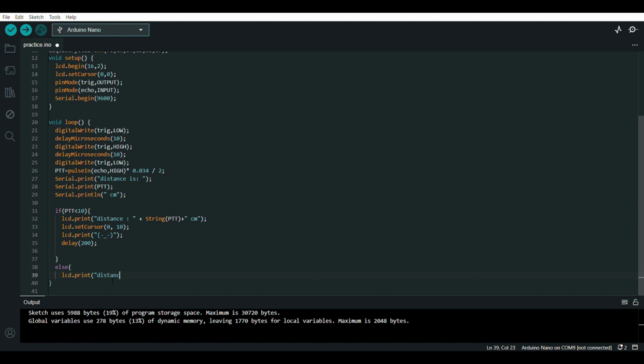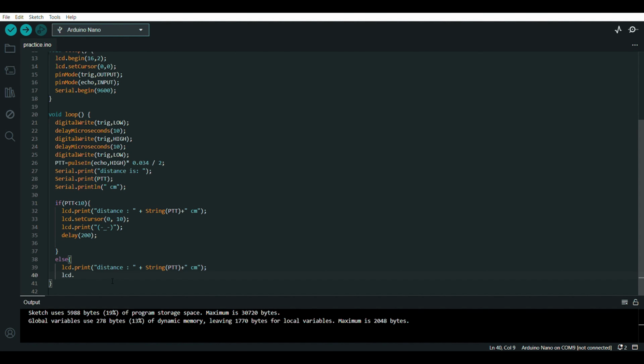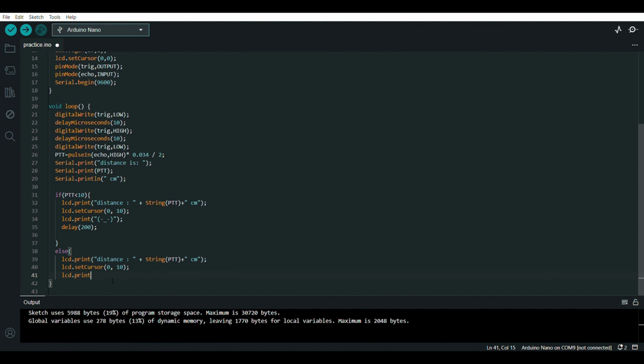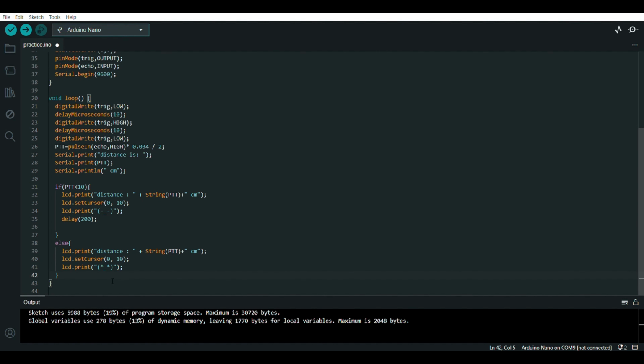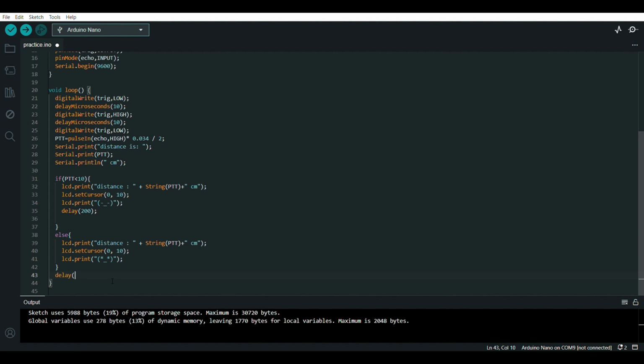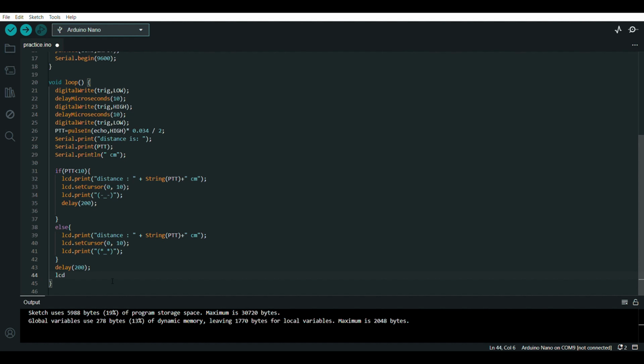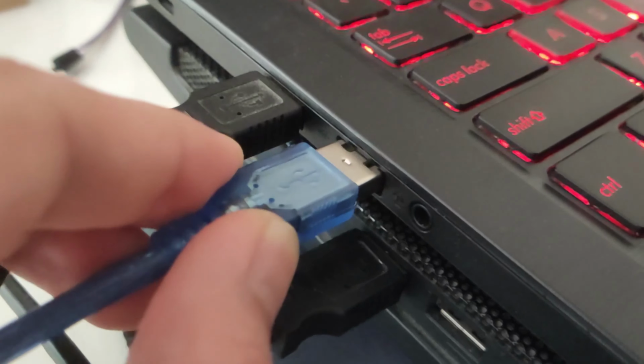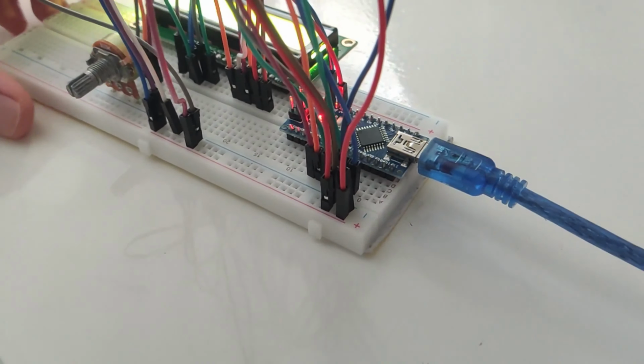Here, I will only use 2 options to switch between states of the LCD, but you can choose as many options as you want for your projects. At the end of your code, do not forget to clear the LCD screen so you can keep it neat and clean for the next iteration of the loop. You can do that by using a method called clear, which clears everything from the LCD screen. Now everything is set. Let's run and see our results.